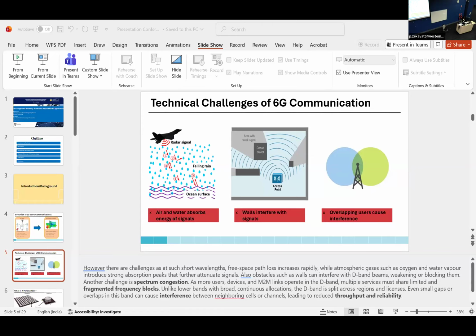And then when the bottom diodes were turned on, the stop band shifted to 148 gigahertz, and the other stop band near 126 gigahertz became deeper attenuation. And then when the top diodes were on, the stop band was found at 148 gigahertz as well. And also when all the diodes were turned on, it shifted down towards 142 gigahertz. And also a band pass was found at 126 gigahertz when all the diodes were on.